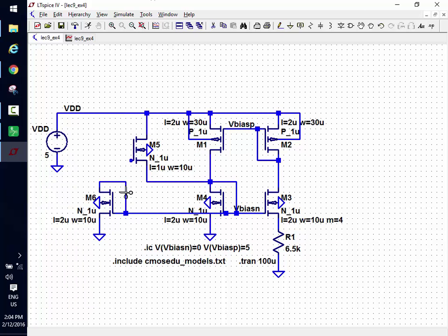And I have to be careful because I don't want a diode connection and waste time because it won't work. Does everybody see that? So if it's not started up, how much current's flowing over here? None. Does everybody follow that? There's no current there, so there's not going to be any current in here either, is there?